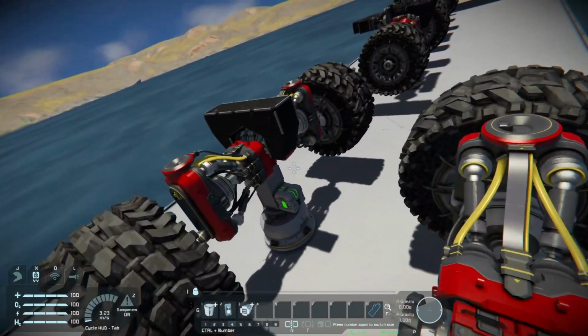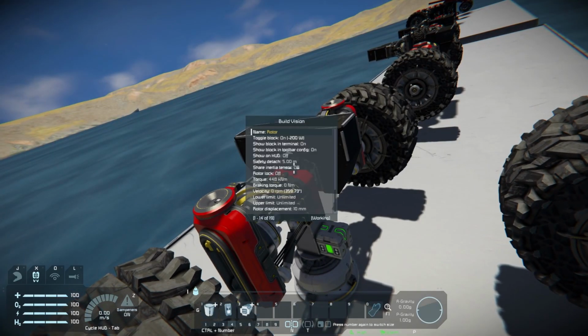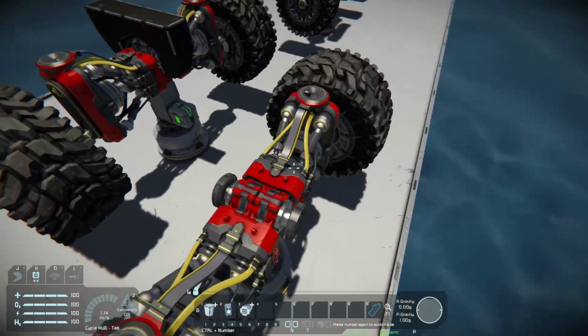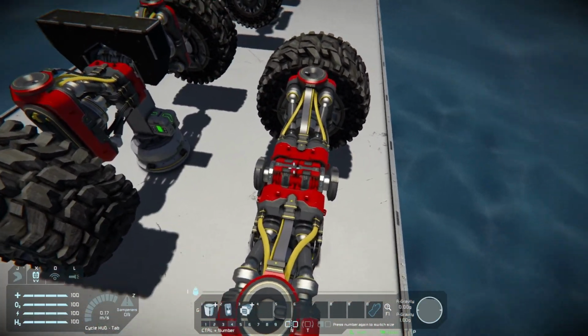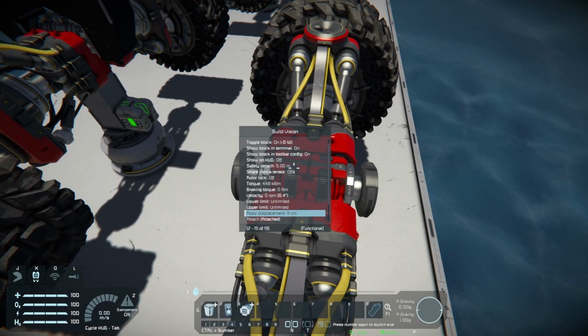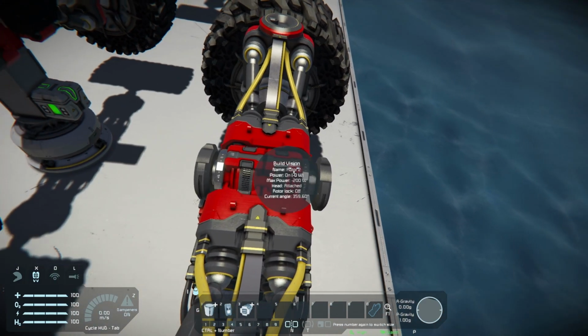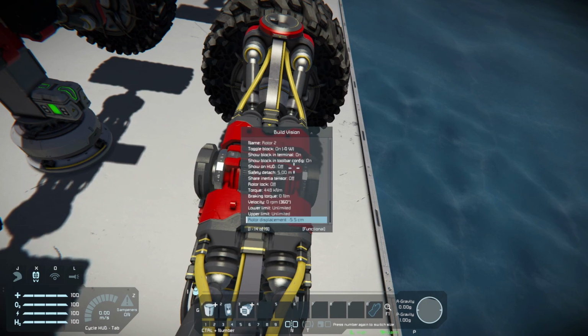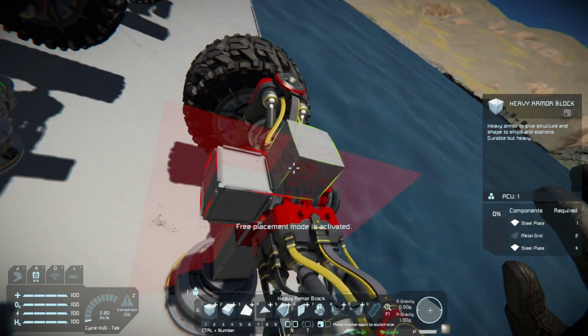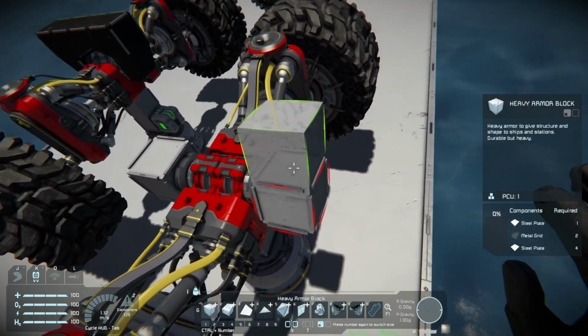So, what I would recommend you do, from what I remember, is just 10, isn't it? Yeah. So, I'm using Build Vision here to make it easier so that I'm not messing around in terminals. Some people were asking what that was. So what I tend to do is move the rotor head in until it's 10mm on both sides. Out all the way, and then into 10. And then from there, you want to place a block like that. You want to place a block like that.